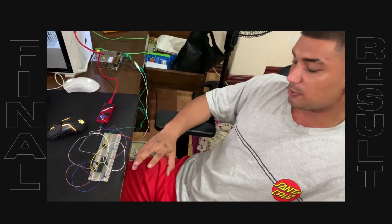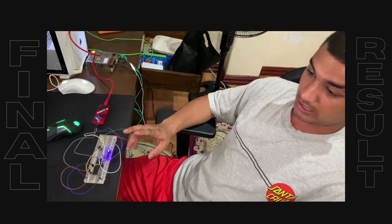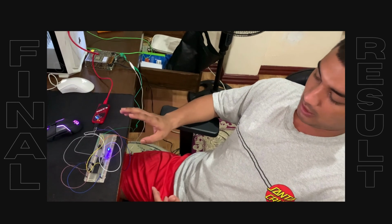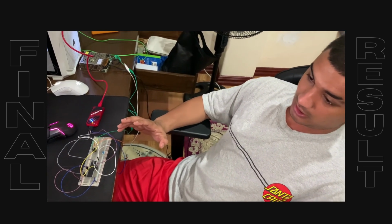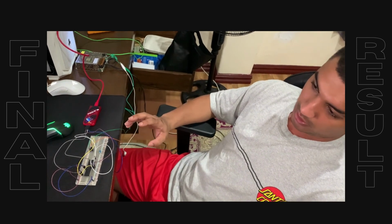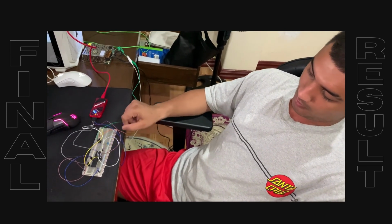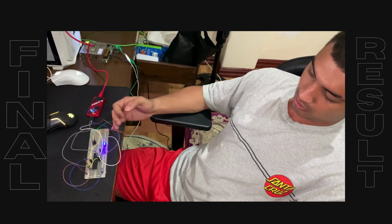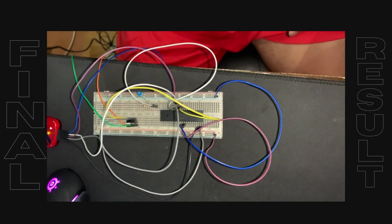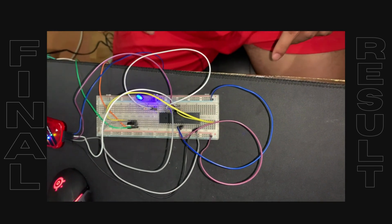In the first part of the experiment, we have used delay and polling, and for the last part of the experiment, we have used delay and interrupt. So in conclusion, we can achieve both delays using polling and interrupt. So in this part I will show you that the LED is now blinking at 2 seconds. It has a delay of 2 seconds.